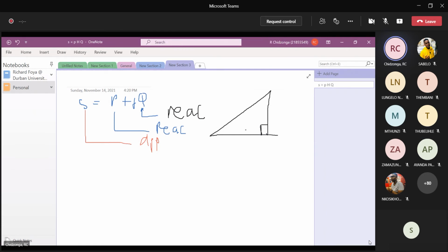All right. Now, if you have these three quantities, these quantities are a point on the complex plane, and they form the three sides of a right-angle triangle, where the hypotenuse is S, the opposite is Q, and the adjacent is P. This angle here, from geometry, we can find it.